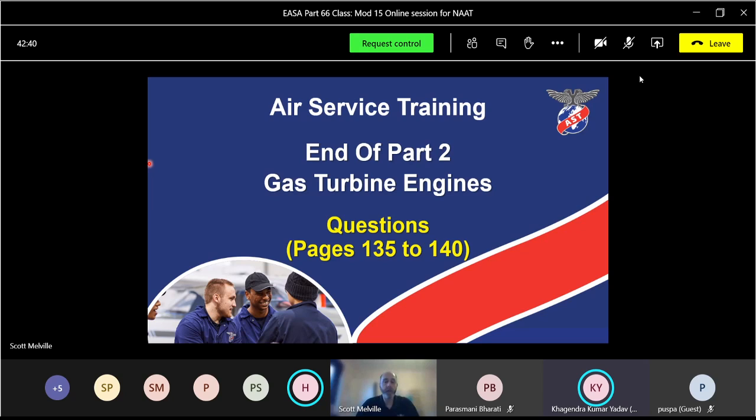Good, yeah. So another engine, we can give air from another engine, supply it to the other one. The APU, which is in the back of the tailplane for most commercial aircraft, or an external ground trolley that has a small jet engine on it, also supplies air to the air start. So a few different sources there. Good. Okay, that's a good point.